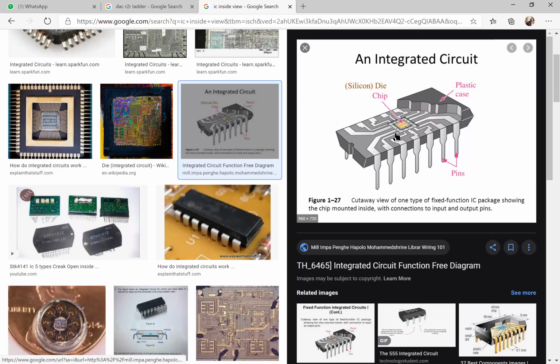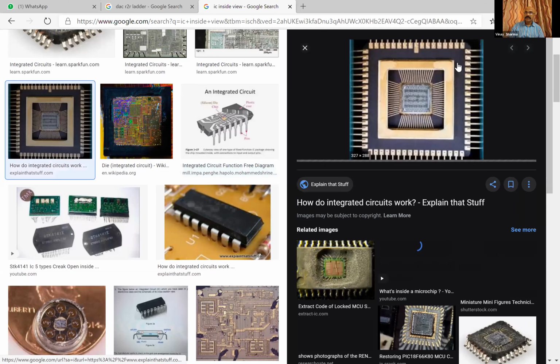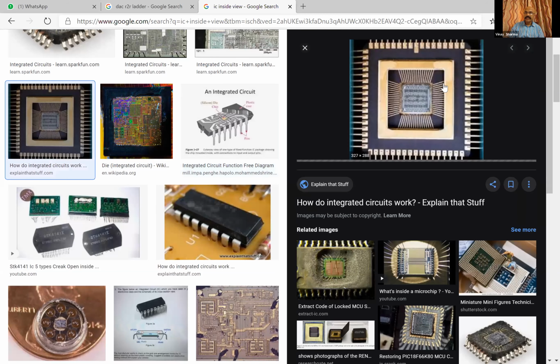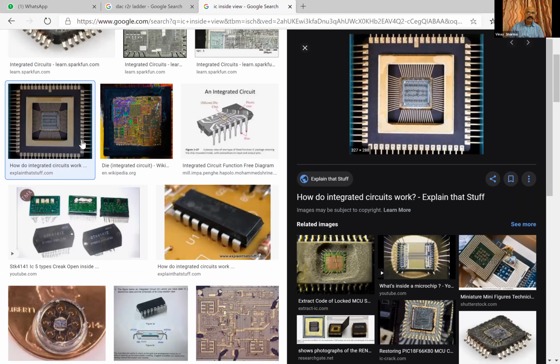All the 16 wires or 28 wires, or whatever the number of pins the IC has, come on all sides of the silicon layout. And from that silicon layout, you short using a gold wire, something like this. All of them come on the inside line, and then you just short it. That's it. This is how it is.